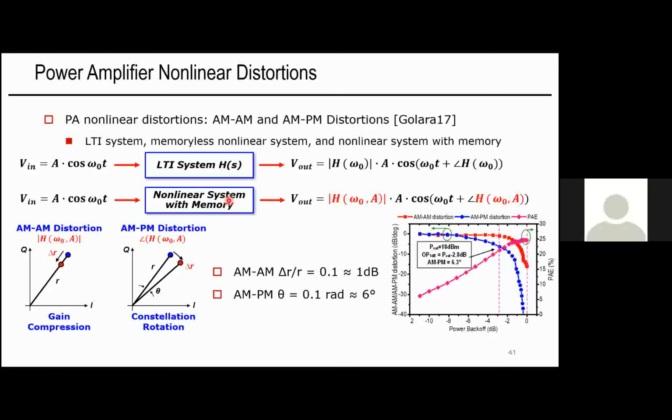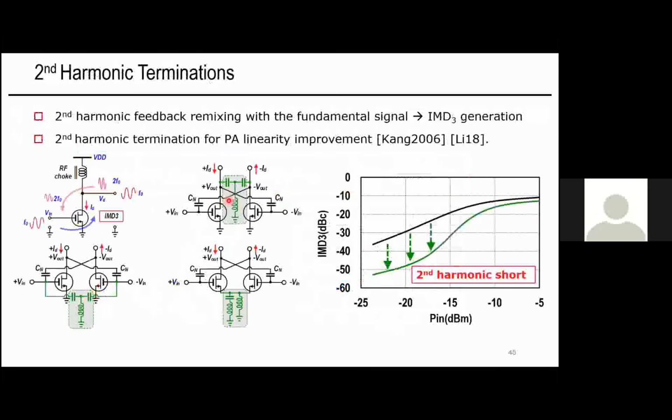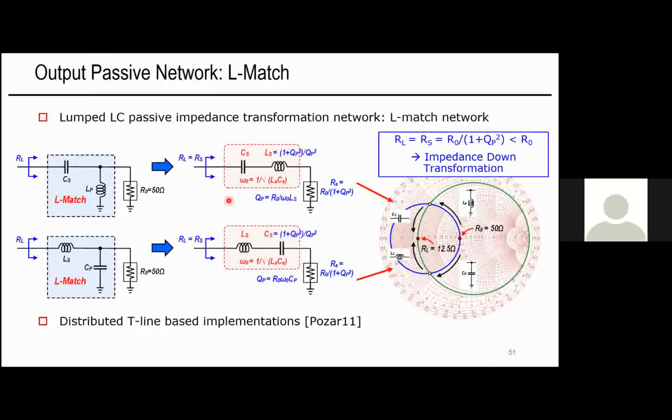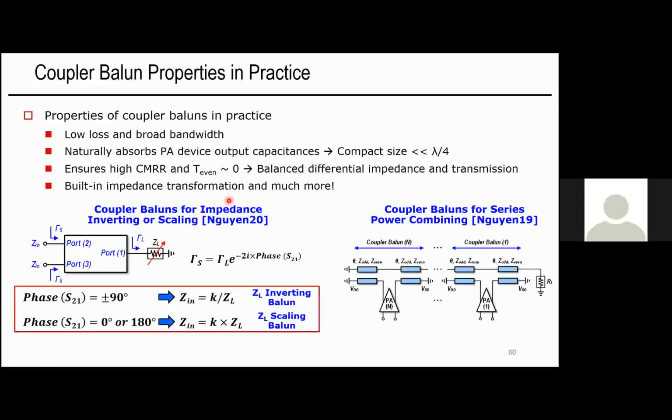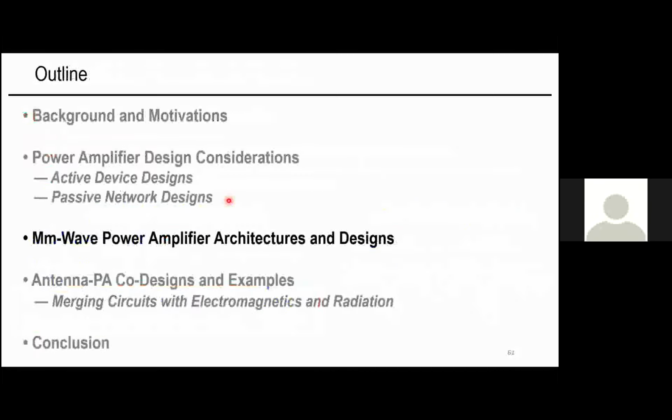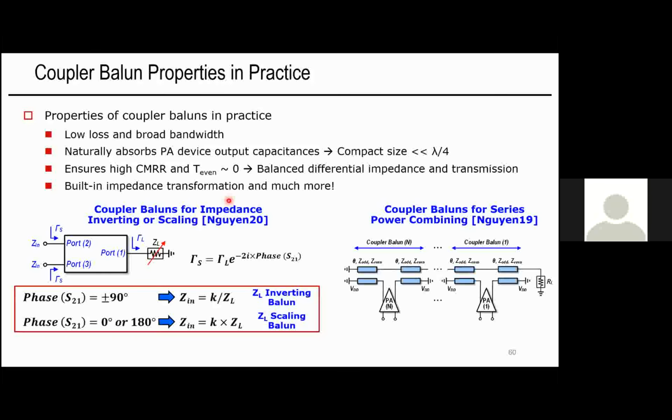Hi, Professor Wang. Thank you for your presentation. My question is in terms of the balun design, especially the coupler balun. I think it's most suitable for CMOS technology, right? Because for gallium nitride, usually there are just two metal layers that we can access, at least for UMS or WIN Semiconductor. They just have two layers of metal, and why is the common ground? So it seems very hard to design the transformer using GaN technology.